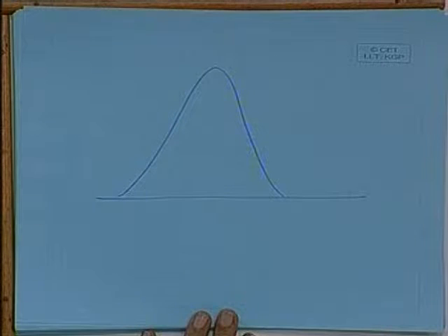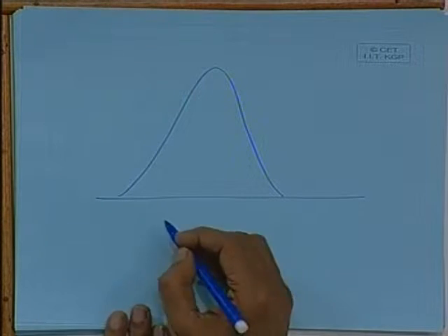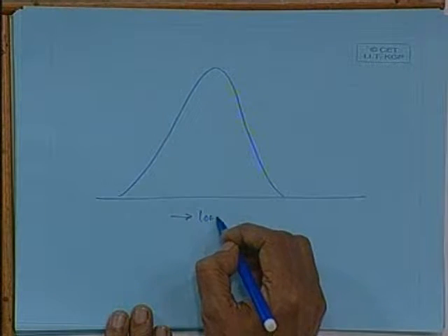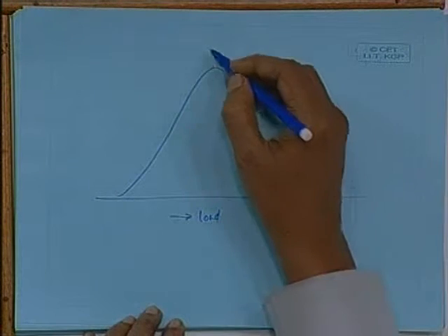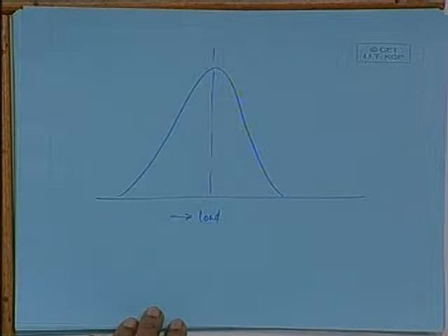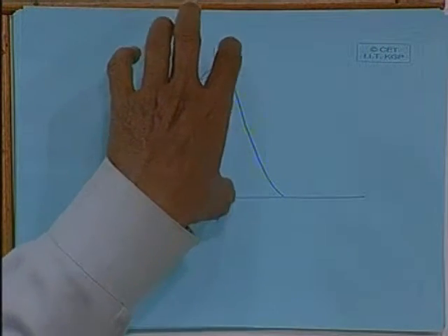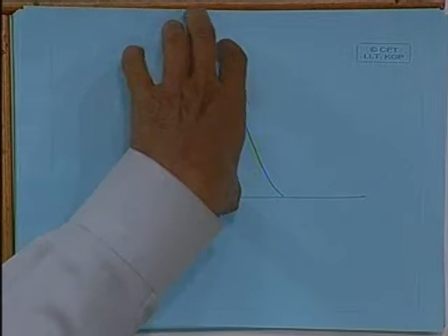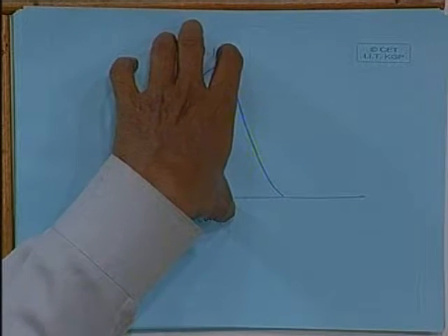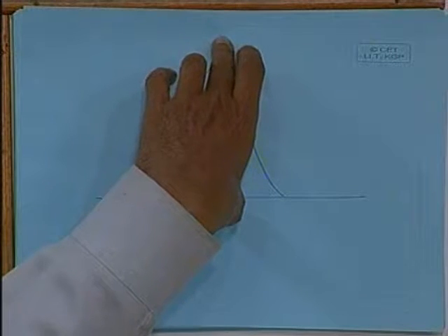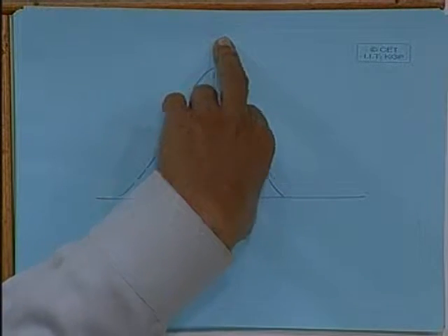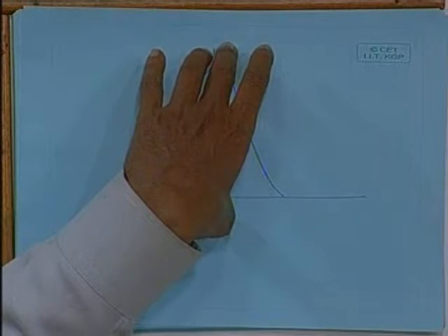Inverted bell. Okay. If this is my direction of load, magnitude of load, I will have a mean value. Maybe this value is the one given by classification societies, that is the static bending moment superimposed by a hypothetical wave bending moment. We are not sure of that, but it could be.